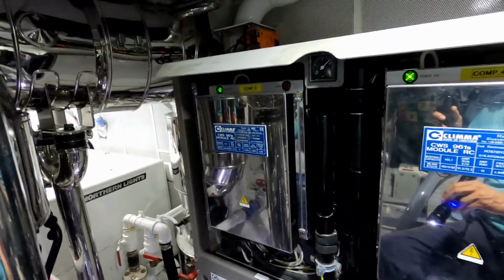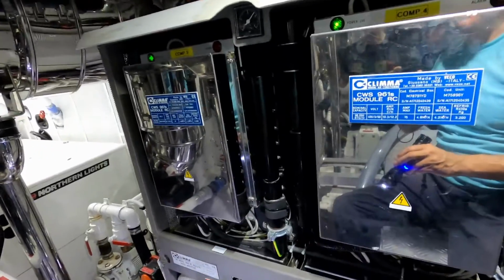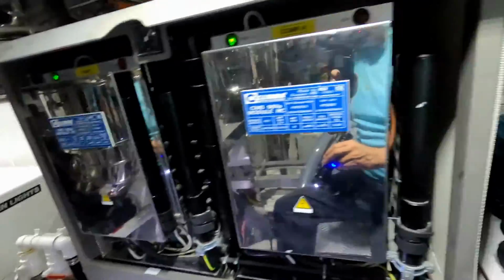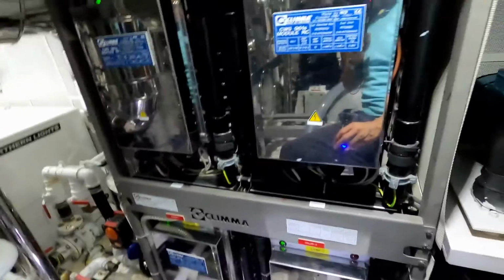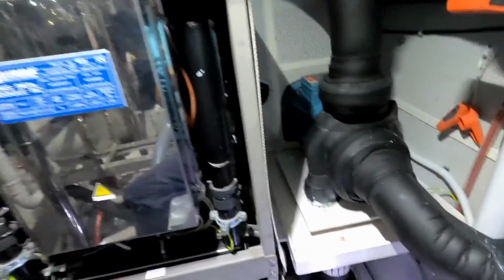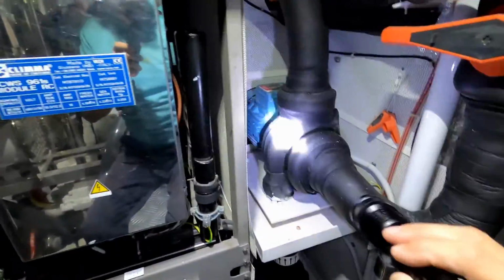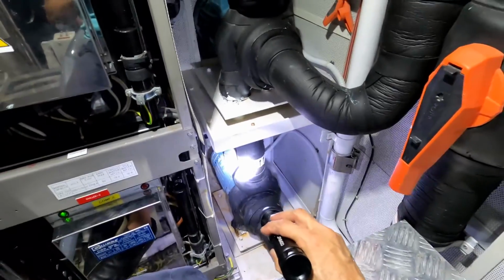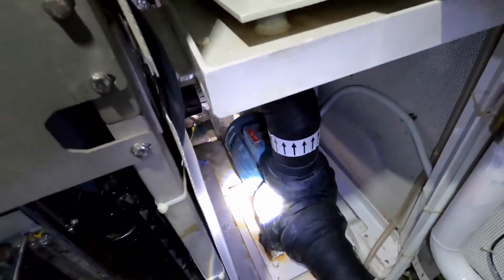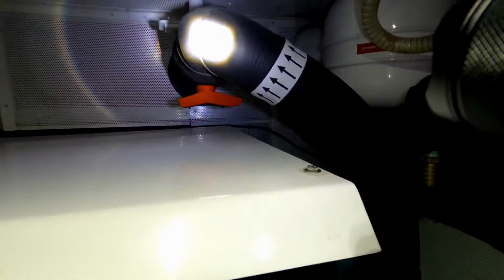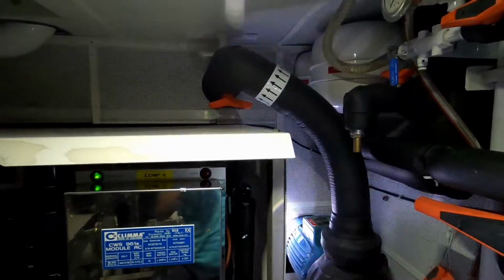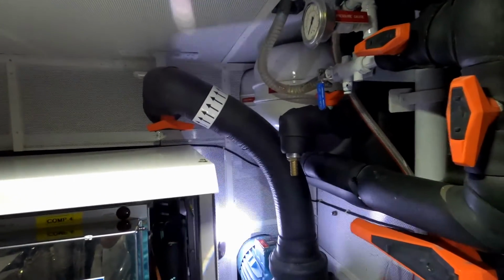The raw water cools the compressors, cools the coil of the compressors. And after that, the raw water goes outside at the back of this wall. Behind those compressors is the evaporator, and the evaporator cools the chilled water, and those are the pumps for chilled water. This is the main chilled water pump, and this one is the backup chilled water pump. And this is the chilled water that goes up into the air handlers, and each air handler has a fan in front.